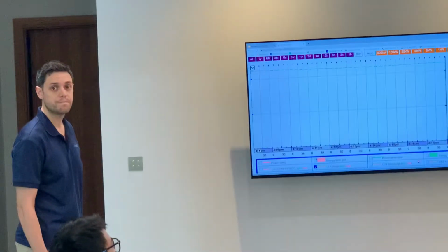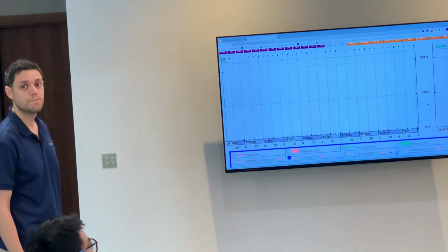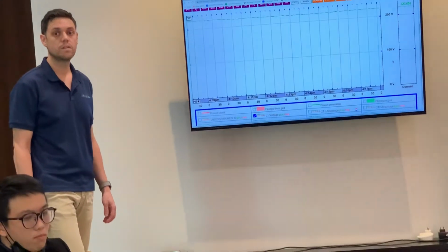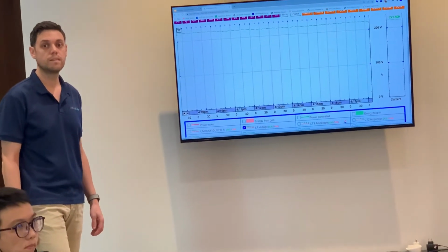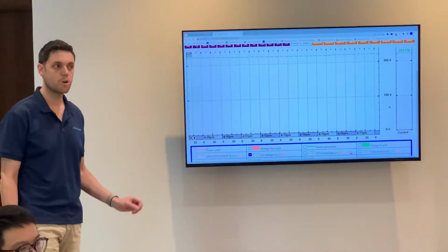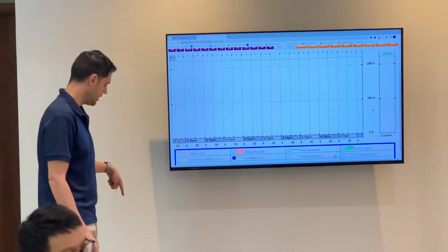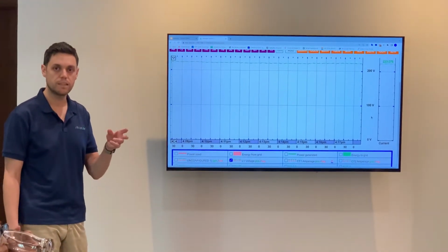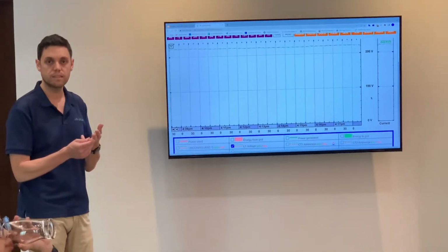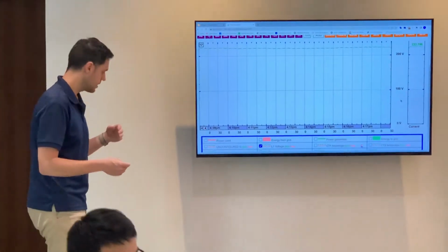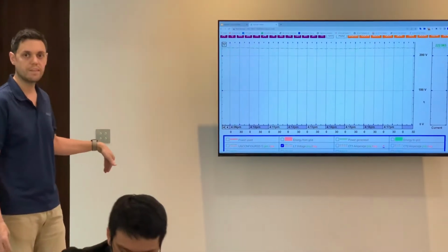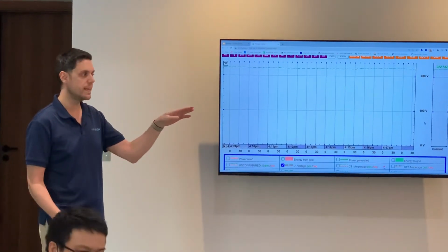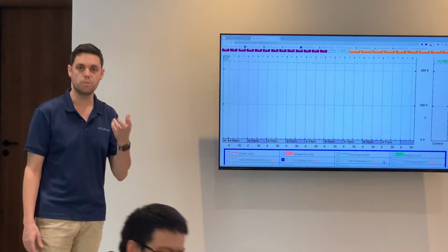So Maxim, basically we have two types of things, right? Like for the solution, one is the meter, and one is the CT. Yeah. So basically, the eGauge reads directly the voltage that's coming into the building through the different phases, right? And then from that, we're able to measure the actual current from the CT. Okay. And so the eGauge does the calculation, which converts it into watts.